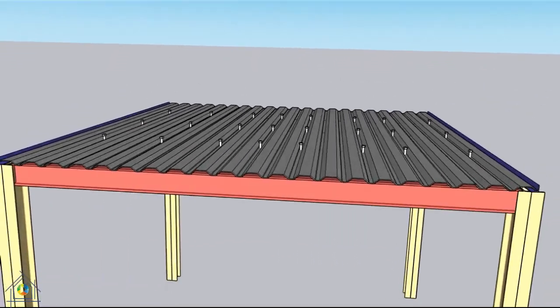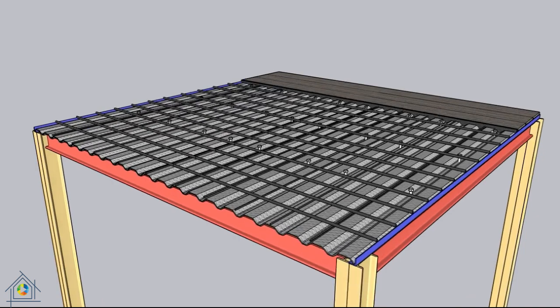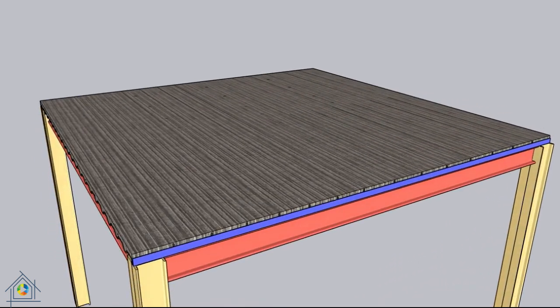Concrete in slabs is prone to cracking due to thermal shrinkage and thermal expansion. For this reason, first, the shrinkage and temperature reinforcements are implemented in a grid, and then the concrete is implemented with a minimum cement of 250 kg per cubic meter. The thickness of the concrete and the details of the reinforcements are determined based on structural calculations.